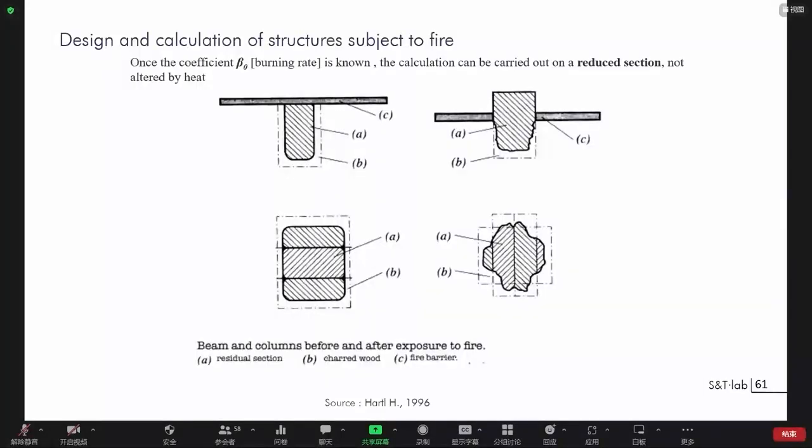And as you know this, you are able to calculate what will appear as the resulting geometry of a member when you have fire. And indeed, the stake will be to have as little surface of timber as possible. And if you choose a very complex geometry with a lot of surface, that's very nice to see, but it's a disadvantage against fire.